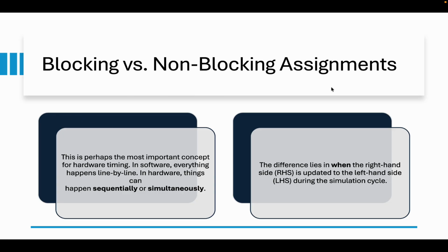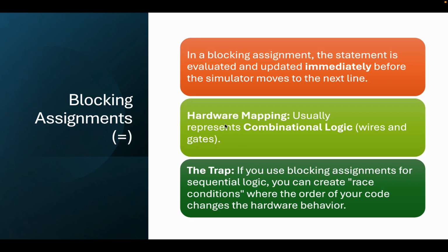Blocking versus non-blocking assignment. Blocking: think of it like a standard programming language where one line must finish before the next begins. This is perhaps the most important concept of hardware timing. The difference lies in when the right-hand side is updated to the left-hand side during the simulation cycle. We'll understand it in detail.